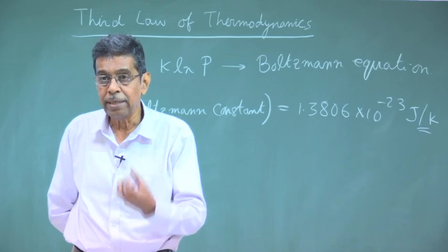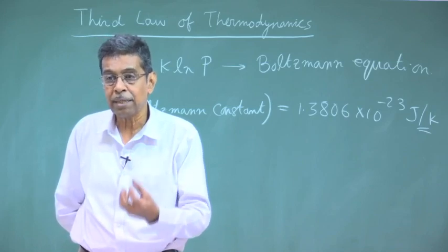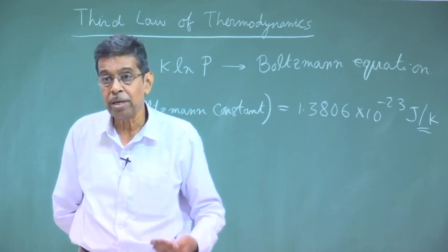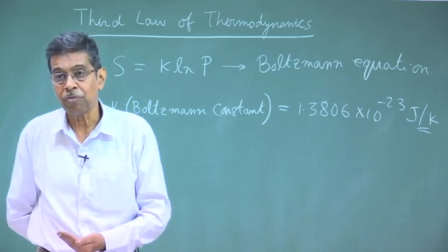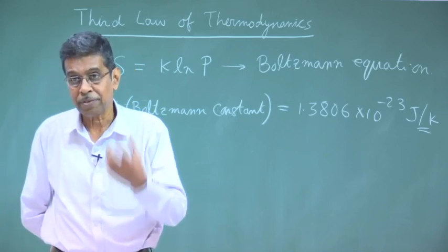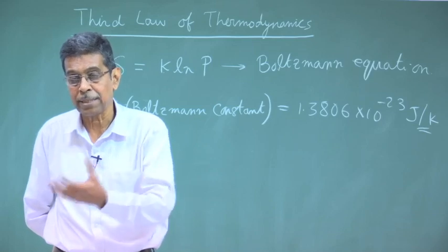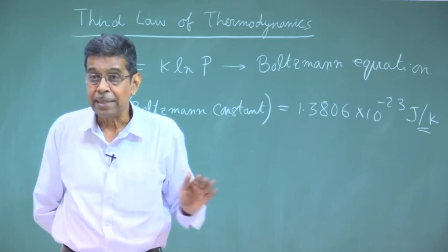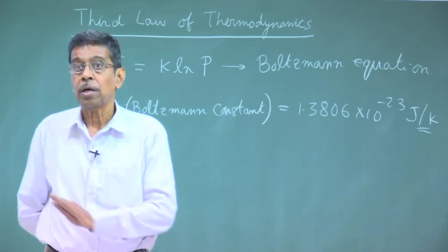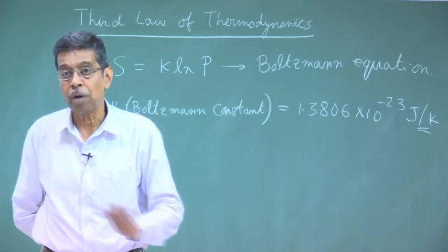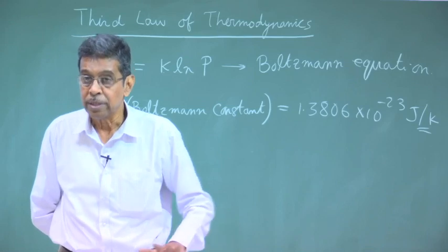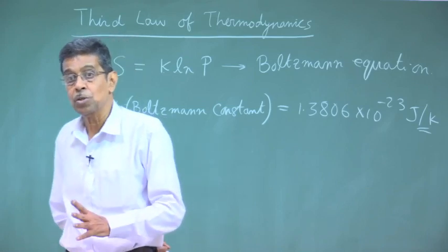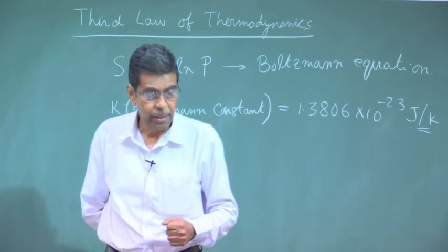If you read the thermodynamics of reactive systems, you will see it is very important to have a common base for calculations of entropy at different states of the substances, known as reactants or products in a chemical reaction, and that base is the zero absolute temperature base where the absolute entropy is zero. This is of very practical use in engineering calculations.